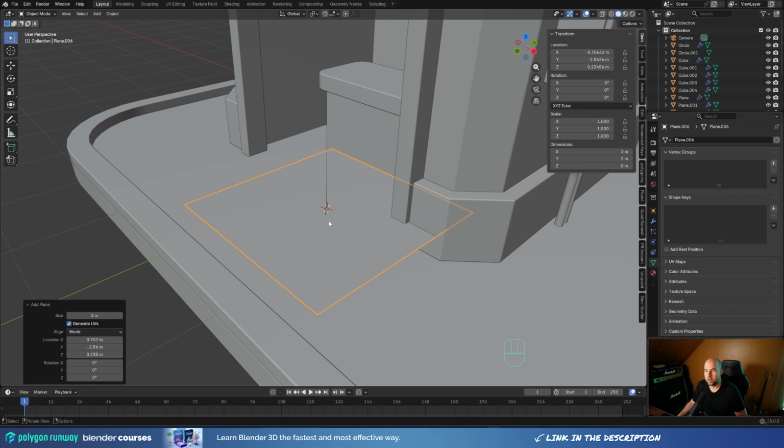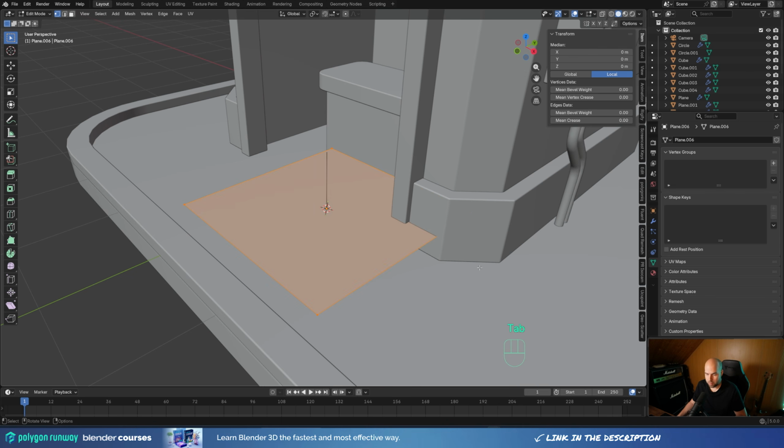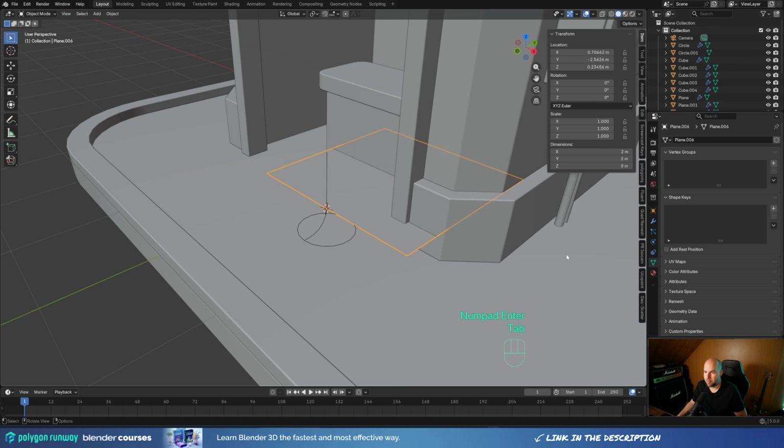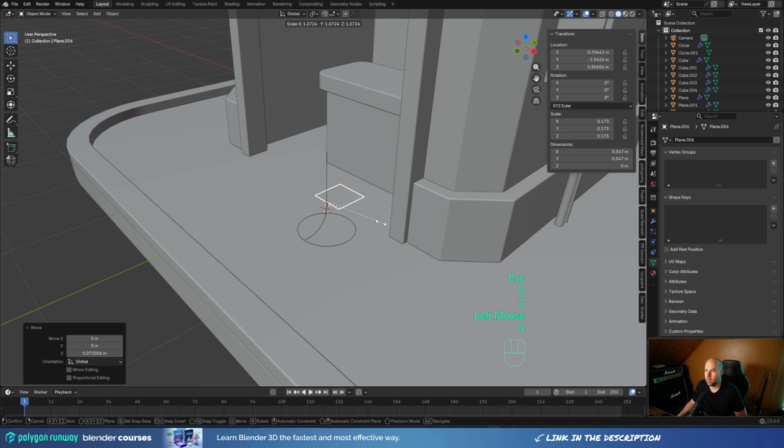And now again we'll use the position of the origin point to manipulate the geometry. So let's tap into the edit mode, press G then Y and 1 and confirm with enter. And now if you tab out and scale according to the origin point, you can do something like this. And now we can press G then Z, move this higher up, maybe make the scale a little bit larger.